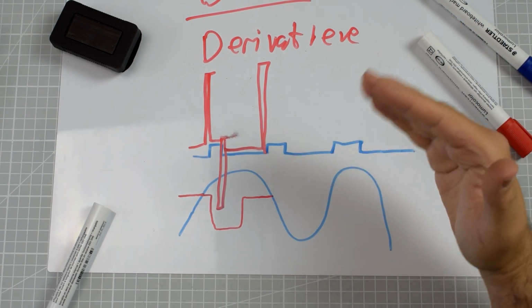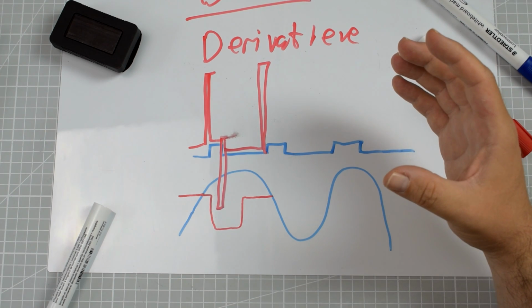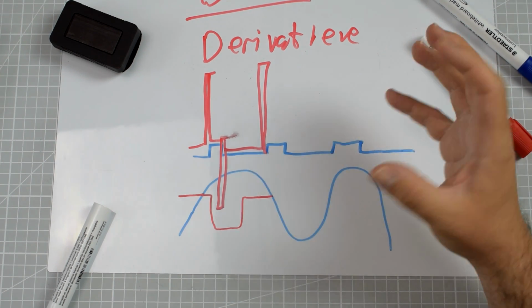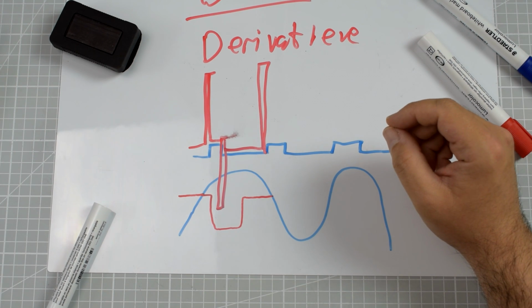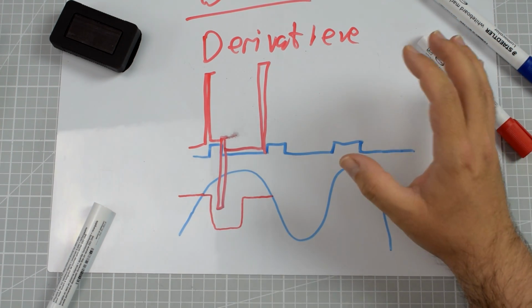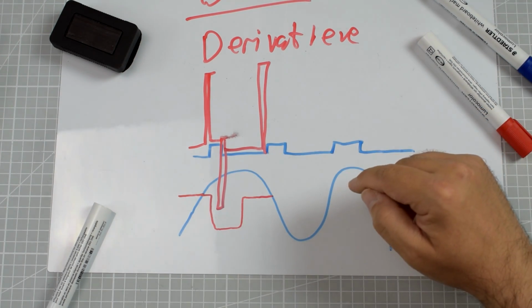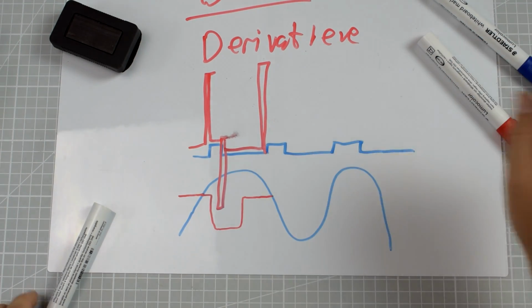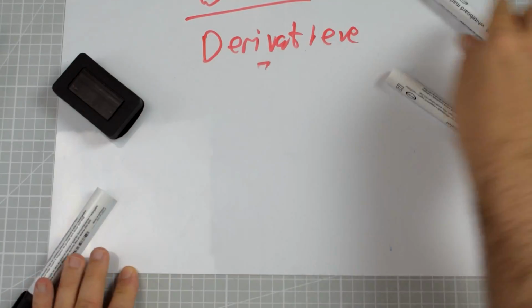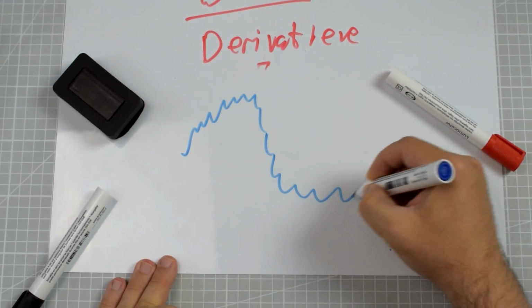Why? Because the output generated by the D term component of the PID depends not on the amplitude of change, not how fast you rotate around one of the axes, but on how fast the signal changes. And if the filtering on the gyro signal is not really perfect, a lot of noise can be introduced into the signal, because our signal will be looking something like that.